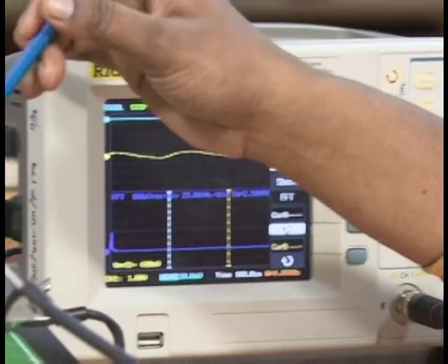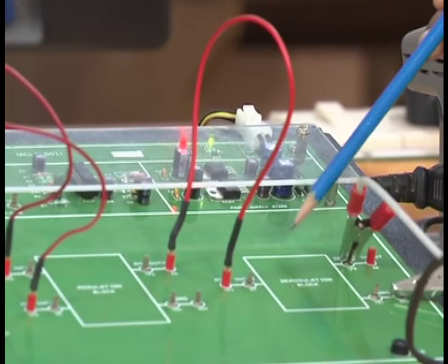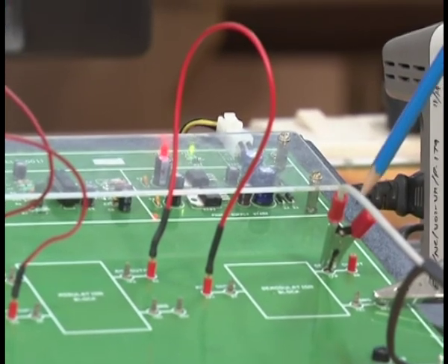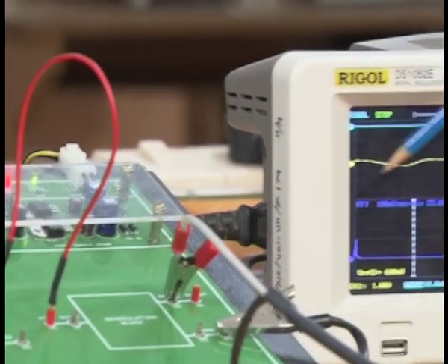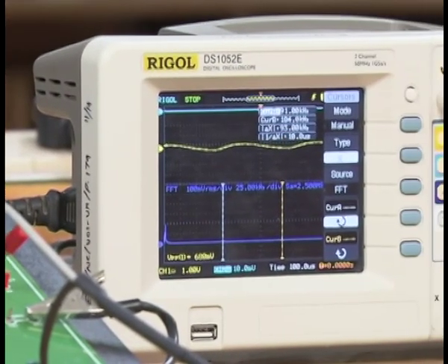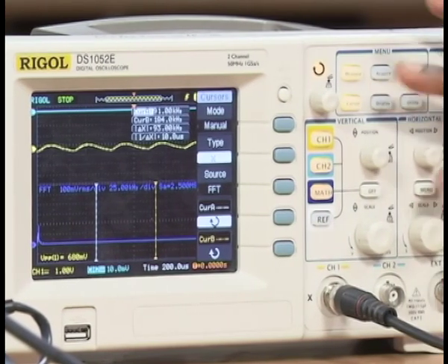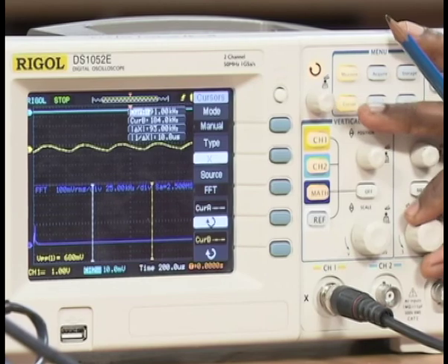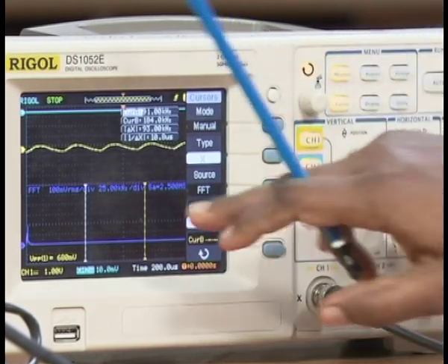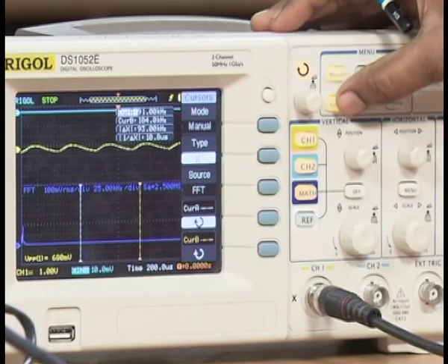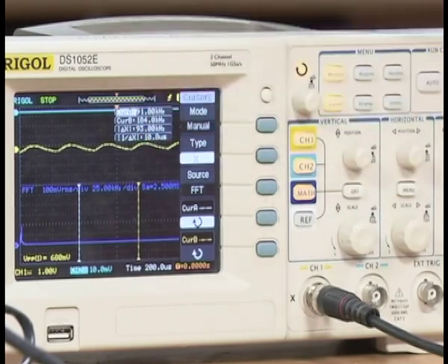For the demodulator block, we have the AM modulated signal as input, and the output is taken across the load, that is the RL resistor. This is the message signal. We have set the message signal to be about 2 kilohertz, but because of the ripples and the RC time constant, this is measuring this. I just adjust the cursors to see the frequency of the demodulated output.